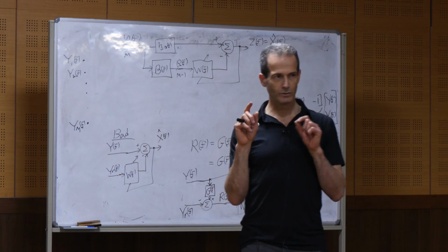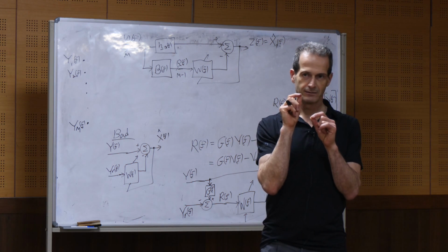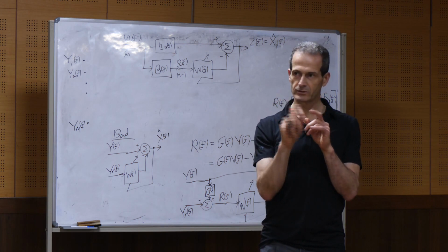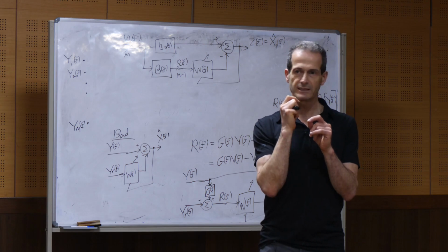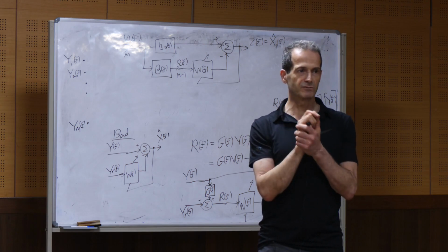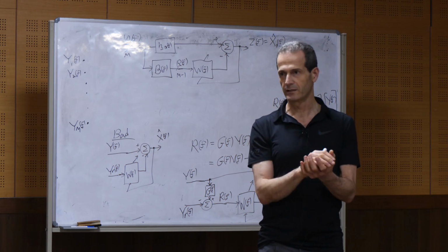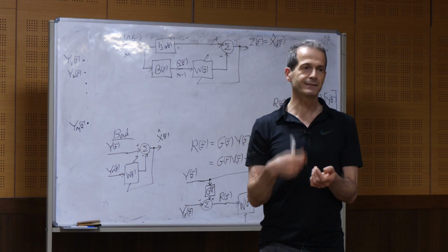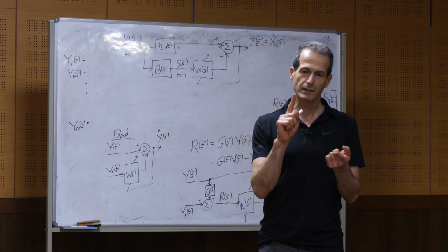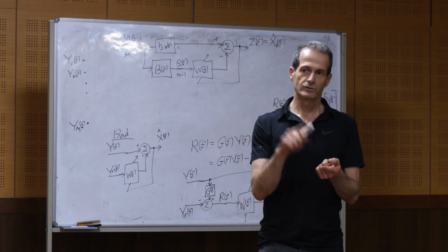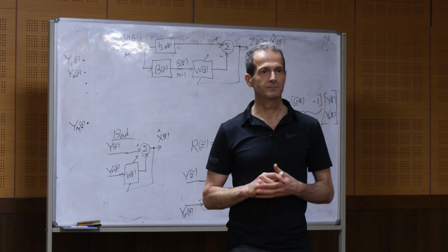So I remind you, what do you do with ultrasound? You transmit a signal, you get it back. Okay, so you transmit a signal, you get it back. What happens to the frequency of the signal that is received back from the target? It depends on the movement of the target. So we get a Doppler. And using this frequency difference, we can measure the movement. So this movement gives us a measure of the heart rate.